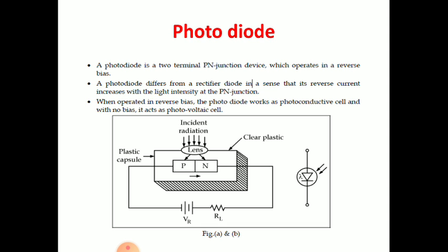The current increases exponentially with voltage. Then in the reverse bias section, we have a reverse leakage current of small value, which is of the order of nano-amps, and it reaches a constant value. After that, as the reverse bias voltage increases, it reaches a point where the diode breaks down. So that is a normal diode.